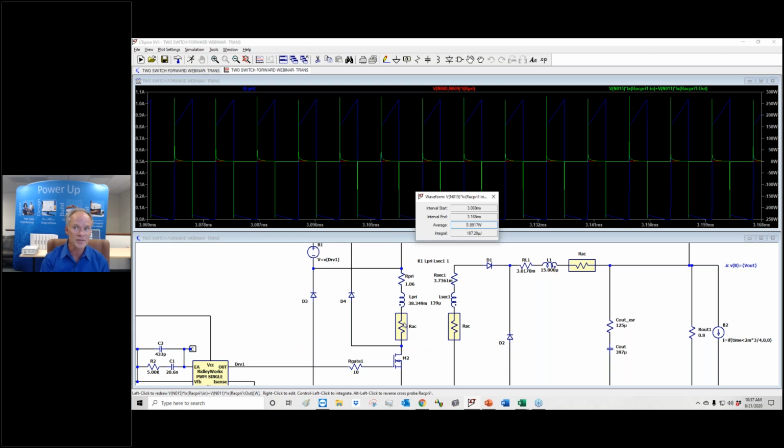You don't have to do a post solution. You don't process the waveform, extract the harmonic, multiply by the AC resistance. This is done in the time domain. So that frequency domain network, changing the resistance in the frequency domain, works just fine in the time domain here as well. So you can see now that we have 2 watts of loss in here.